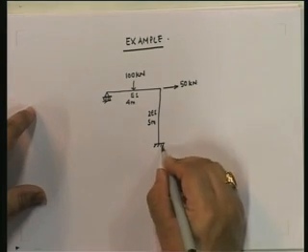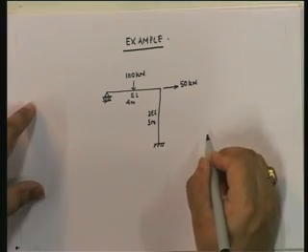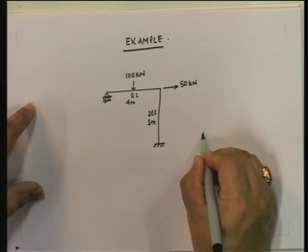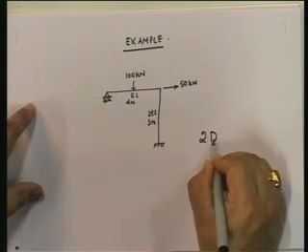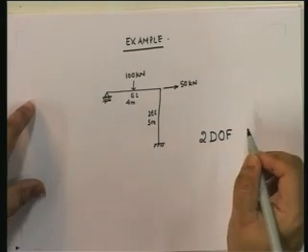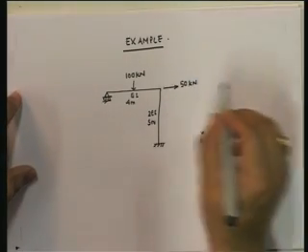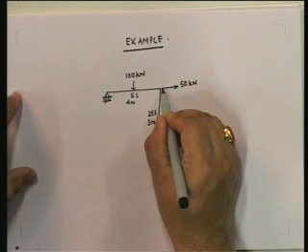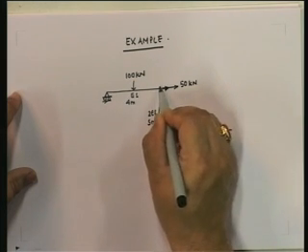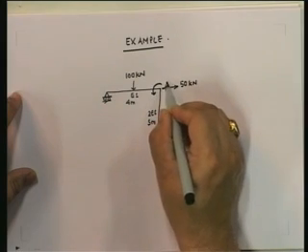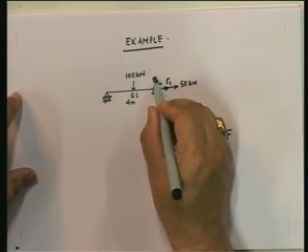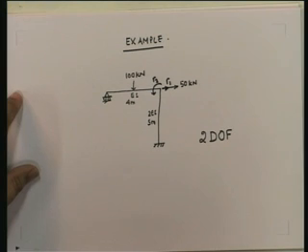Okay, so this is the problem, and here the problem is essentially to figure out the displaced shape and also to figure out the bending moment, member end moments, and the bending moment diagram for this particular structure. First and foremost, how many degrees of freedom? Now I'm going to just state it, and I will expect you to find this out. This is a 2 degrees of freedom structure. Use the procedure that I have developed and establish that these are 2 degrees of freedom. Of course, all the joints are actually rigid. So the displacements are R1 and R2.